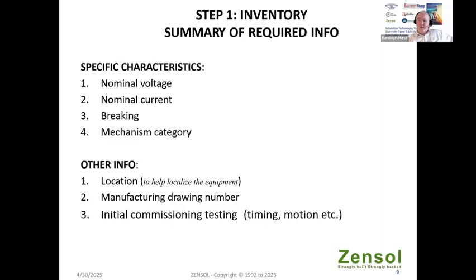I think they were asking, how can you tell the difference between mechanical wear and electrical faults? If you want the electrical faults, you must do your testing online, because this way you can get arcing. If you do exactly the same test offline, you will not see the arcing of the contacts.